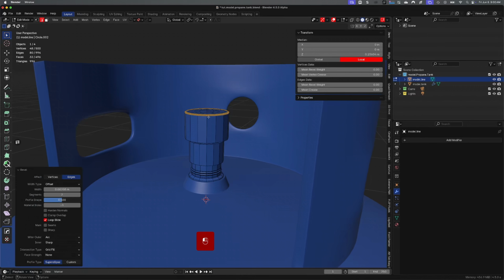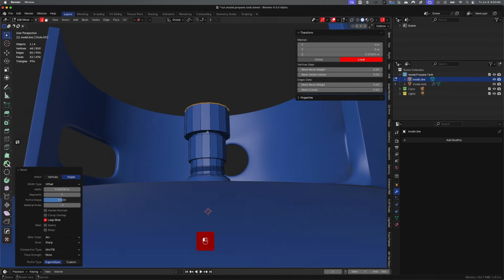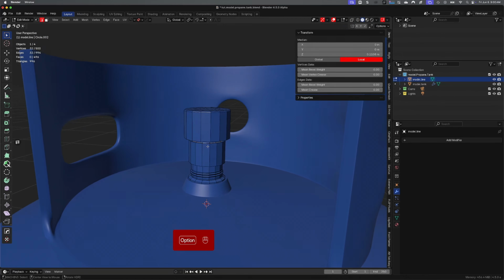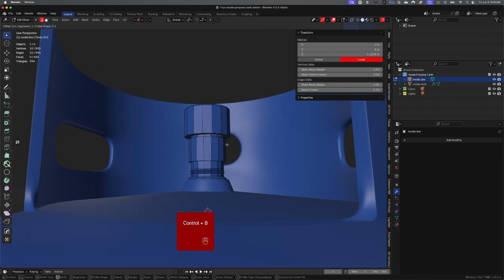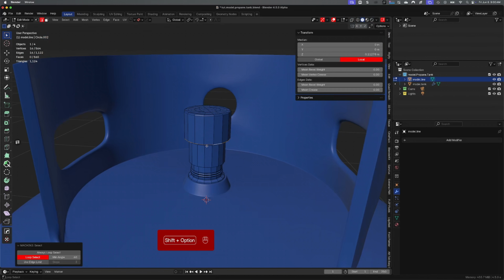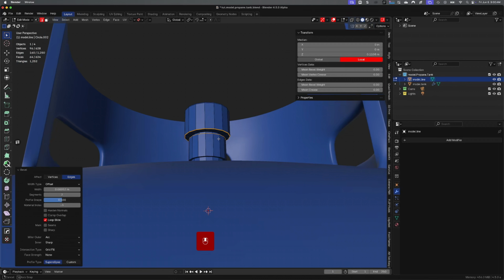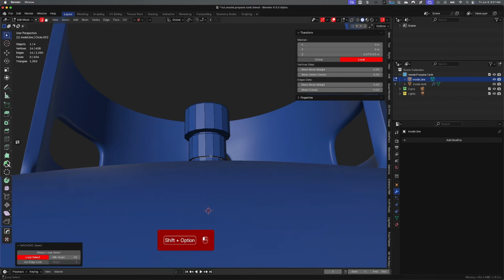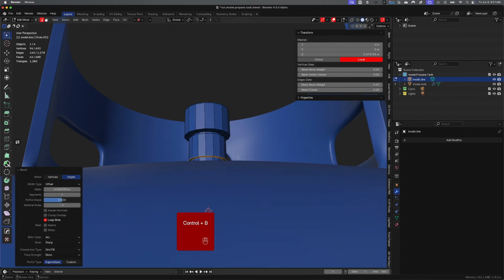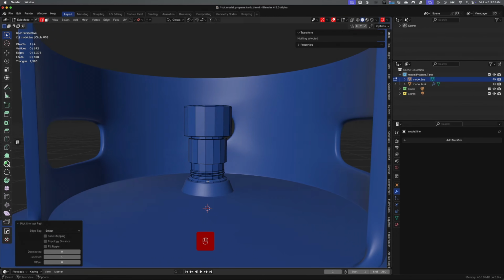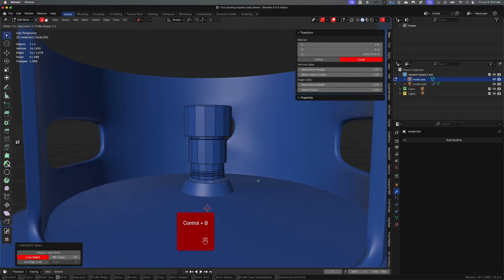And then I'm running bevels after the fact to kind of tighten up areas that I don't want sub D to have that much of an effect on. And the amount of bevel that I'm applying constricts the amount of sub D that will be applied to a particular edge or a particular face, really a particular edge. And that's why I'm doing that. Yeah, it's looking good.